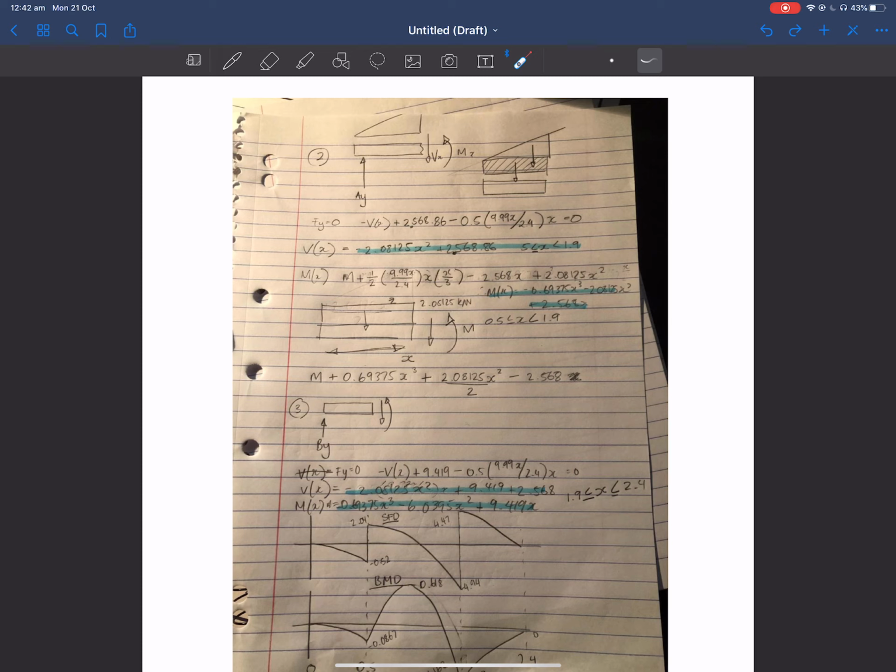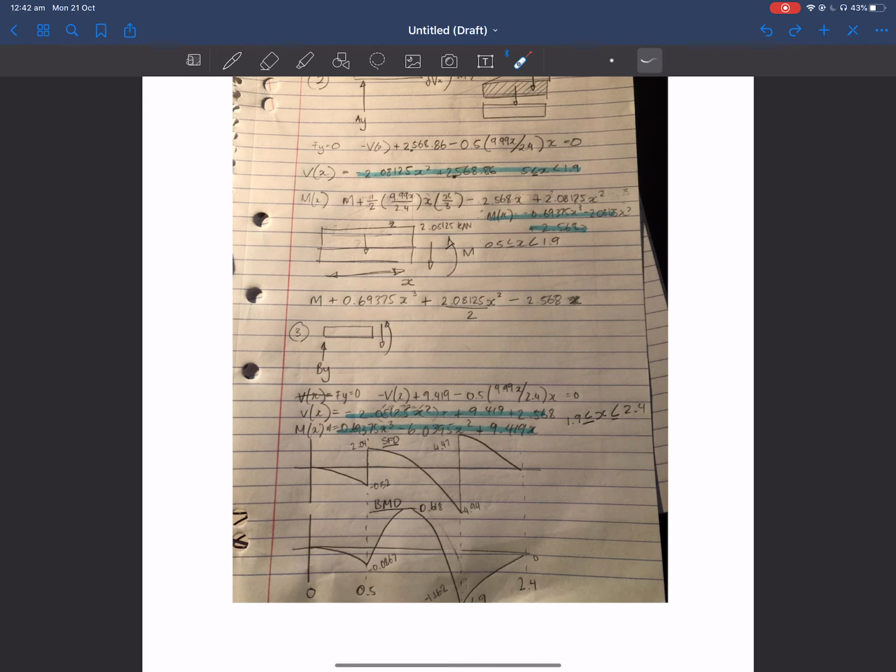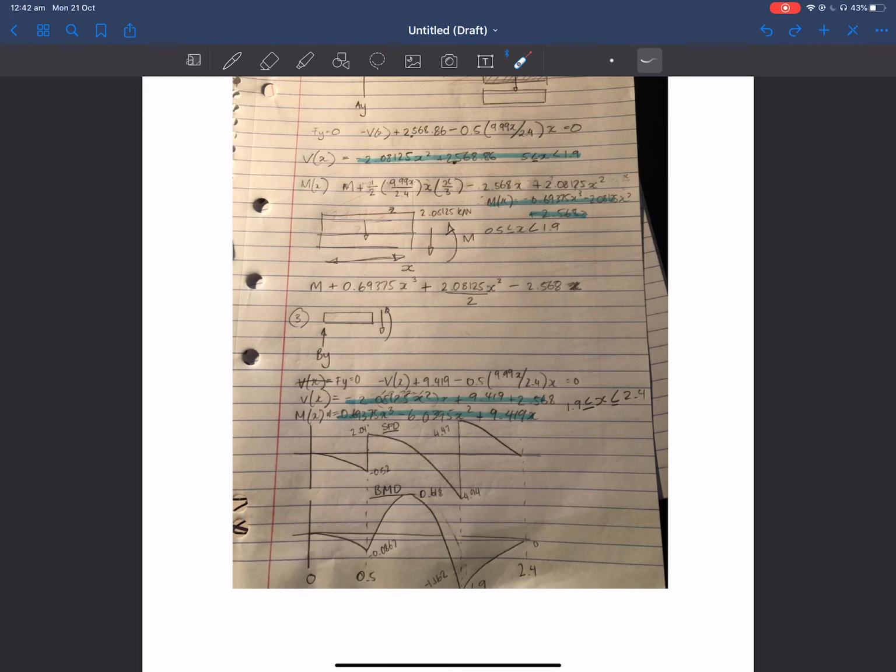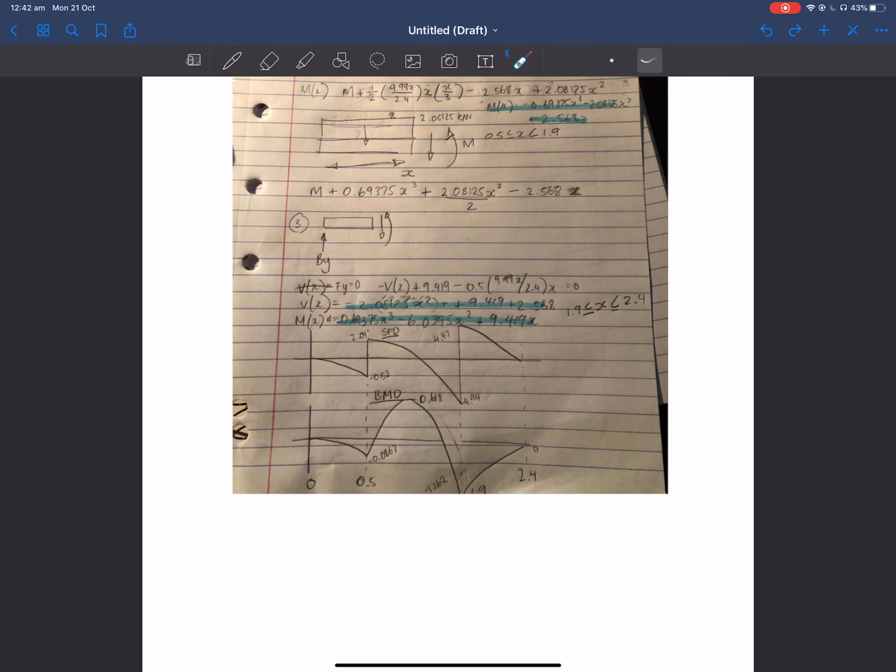Whilst this was a challenge, once I got past the first part, I felt like I gained more knowledge on how to do it, and this got a bit easier. As you can see, the shear force diagram and bending moment diagram kind of looked like that. It looked a bit odd, but I cross-referenced it, and it looked okay in the end. The bending moment diagram had a maximum as well as a minimum, so there would be 2 maximum bending stresses, both compressive and tensile.